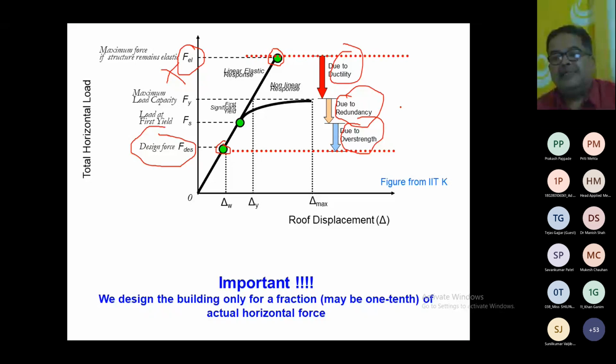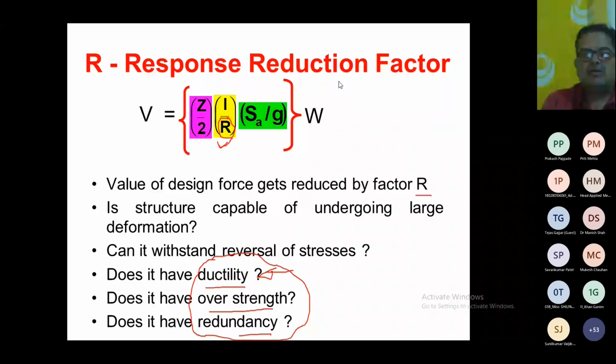So just imagine, with good quality control on site, instead of 25 your concrete has a strength of 28, 29, then it is giving you the overstrength part. Or you can say we have so many overstrength factors, right? So this ductility depends on these 3 parts, right? And basically if your structure is able to undergo large deformation, then it is considered to be ductile and it is able to absorb more energy, right?